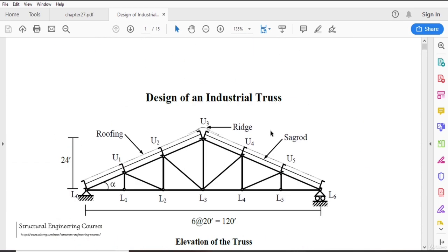So it's okay, the units are not an issue, but my approach is that you should have a solid understanding of the concepts that are involved in the steel truss design. So this is a simple truss section that we are considering here, and the height of this truss is approximately 24 inches. Here these are the purlins, and the end condition is that this is a roller and this is basically a pin connection here.